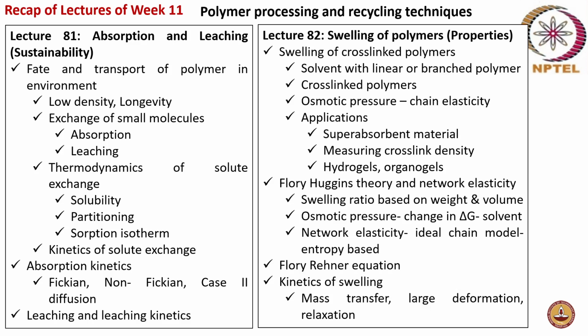The next lecture was on swelling of polymers. So swelling of cross-linked polymers. So solvent with linear or branched polymers, you end up with polymer getting dissolved. Whereas in case of cross-linked polymers, the polymer doesn't get dissolved because of the cross-linking present, and it ends up in swelling of the polymers.